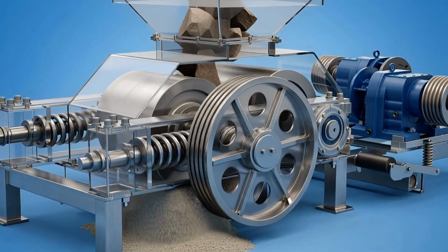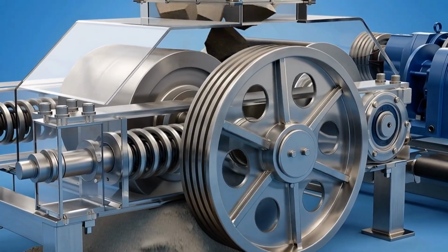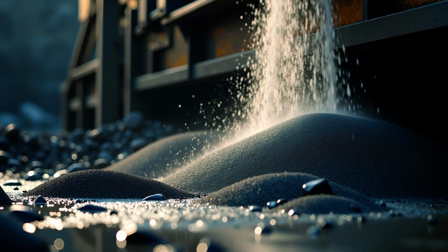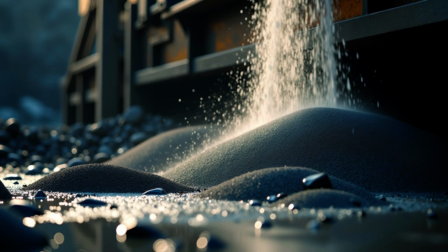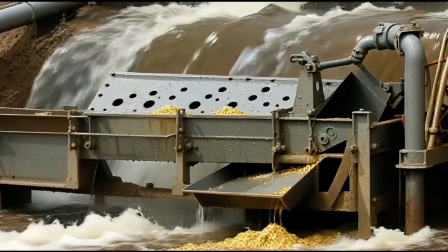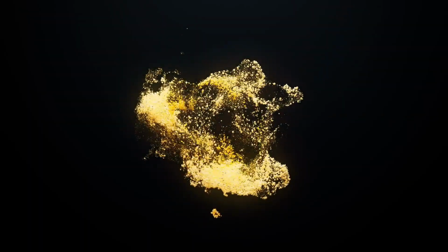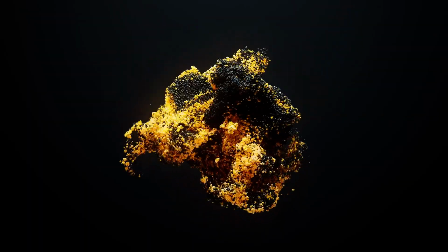An optional double roller crusher can be added after the hammer crusher when finer particle size is required. Once the material reaches this size, gravity-based separation can begin. The first method often used is a jig separator. The jig works by creating pulsating water flow, which causes particles to stratify based on density. Heavier particles such as gold or platinum group metals settle at the bottom, while lighter waste material rises.